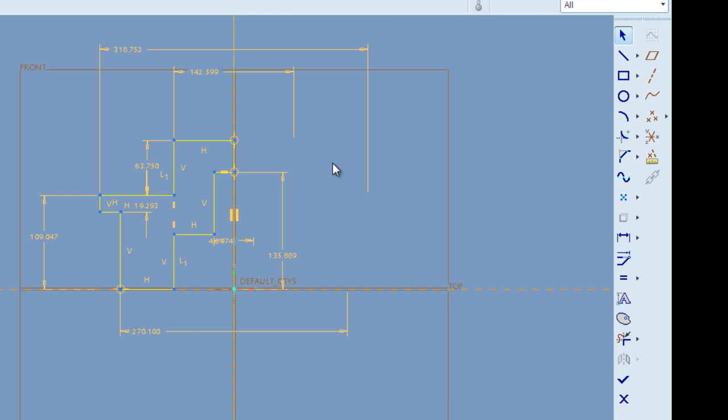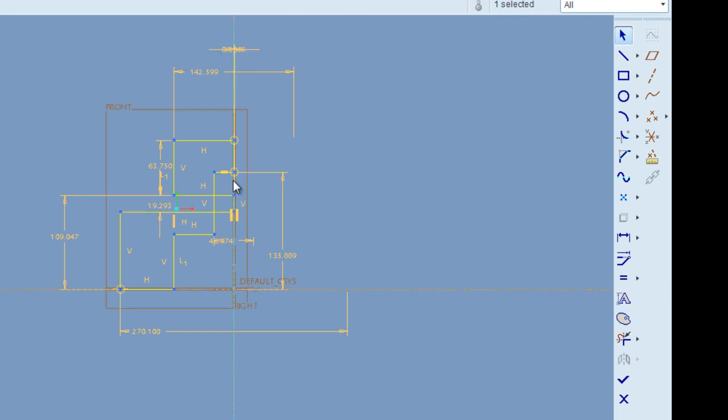We pretty much have all of our dimensions defined as to where we'll dimension from, but we have this arbitrarily large part. Now this dimension here, we want this to be about 0.8 centimeters, or 0.8065 centimeters. But if we set that to 0.8065, you'll see all of a sudden our part no longer has the same shape we want it to have. Let's hit Control Z.